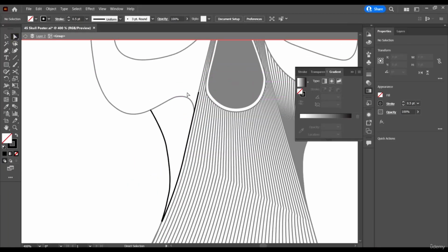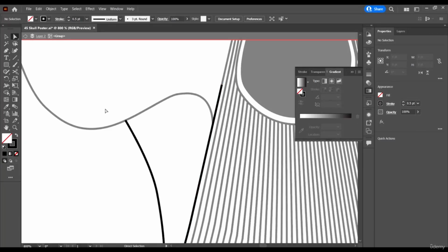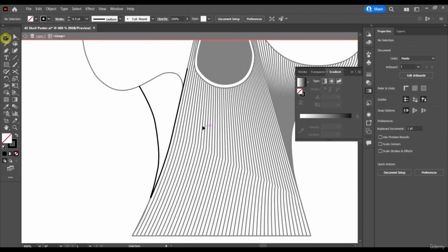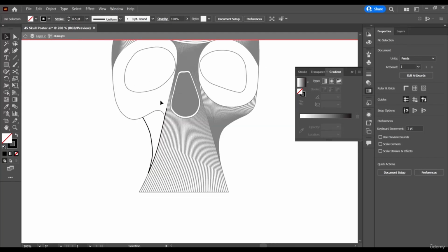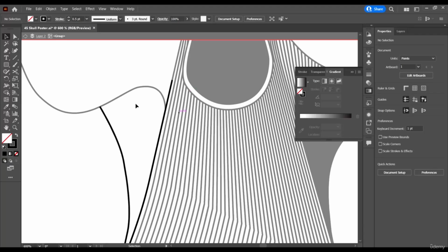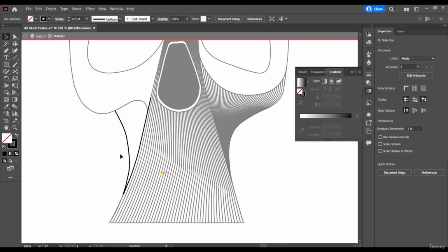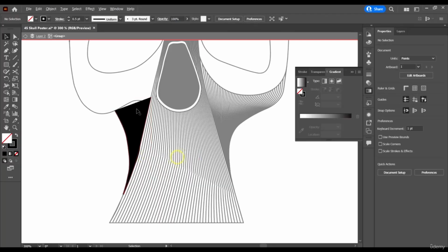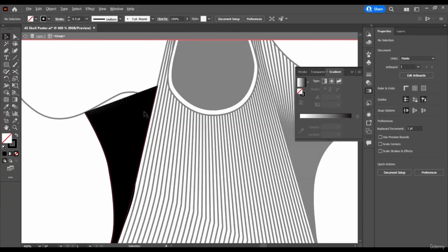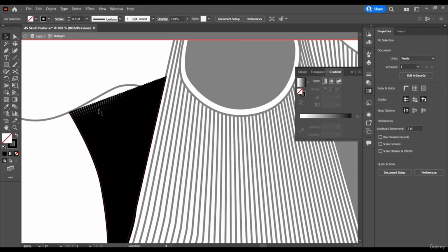Okay, and delete the unneeded parts. For this guy, cut it around here, delete the unneeded parts, and yep, I think we're done. You know what, let me just blend, and I think we'll encounter a little problem here, not a big problem though. Okay, so let's just blend. So select both of them and then make, and we can see that it's too much, but this is the problem I was envisaging.